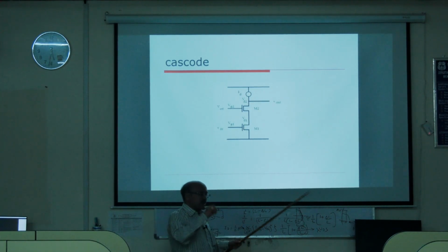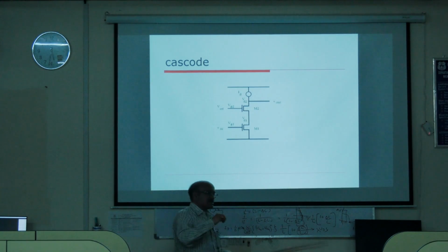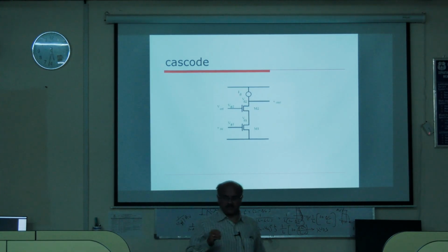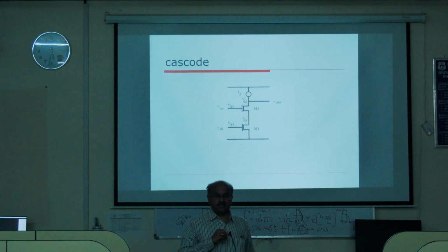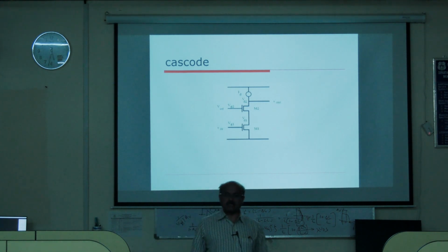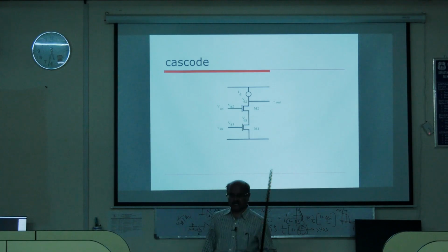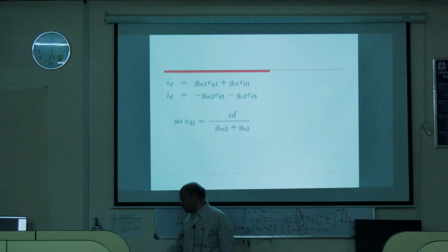So the current is not dancing to the tune of the input signal voltage, but some portion of the current variation is also internally different, which implies that the transconductance GM of this entire circuit is not exactly the same as GM1. It is slightly less than GM1. Mathematically also we can see that. I have given the reasons, and now we will try to see it mathematically.